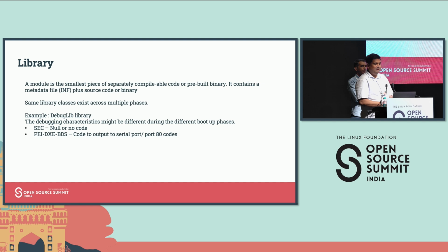Or you might have heard about the POST code, power-on self test, which outputs to port 80. Port 80 is not any physical port or web socket. It is just terminology: the power-on self test codes will be output to that serial console.